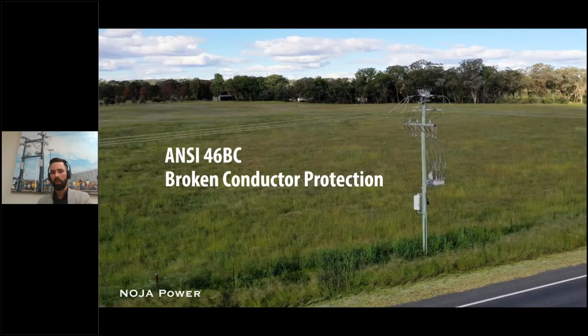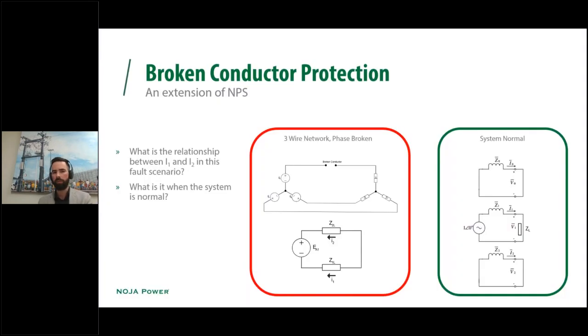All right. So that's negative phase sequence protection in general. What we want to take a look at now is the ANSI 46 broken conductor protection. And this really is an extension of negative phase sequence protection in and unto itself. Because if you take a look at these two scenarios, we've got a system normal on the right-hand side there, and a 3-wire ungrounded network with a broken phase. What is the relationship between your I2 and your I1 in this scenario?